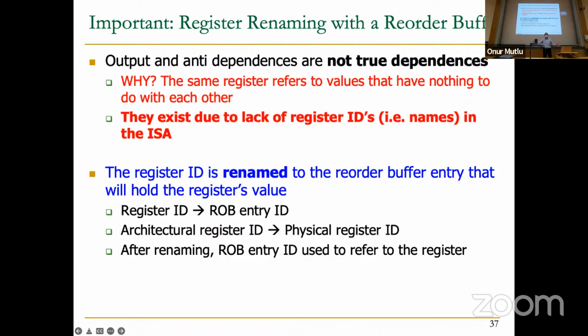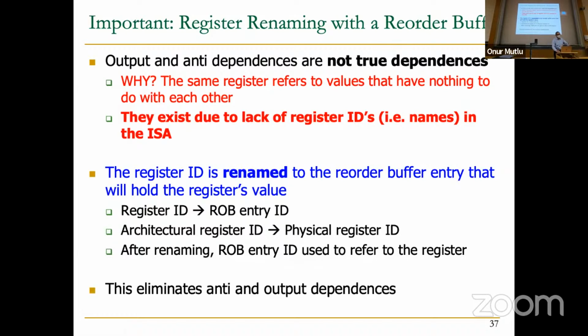Internally, you can make the machine extremely big. But instruction set architecture is decoupled from the microarchitecture right now. So a lot of really interesting things happen with register renaming. You're basically freeing the design from an architectural constraint. You're making it microarchitectural now with the rename. This will become even more clear when we discuss out-of-order execution.